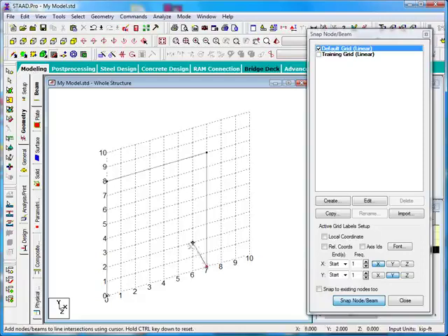And now if I wanted to, I could actually stretch up to the opposite corner, the grid location 0, 8, and click again to draw that first diagonal. At this point I find myself in a little bit of a fix because my next member doesn't want to originate from this particular location, and this is where we'll take advantage of this statement that we see down here on the status bar that says hold the control key down to reset.